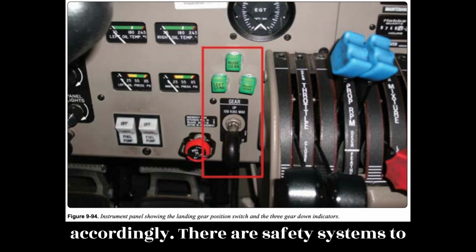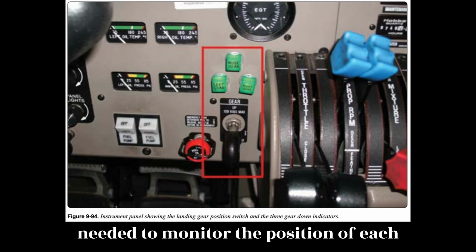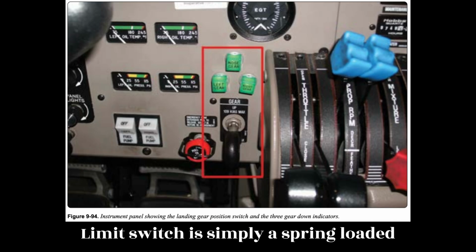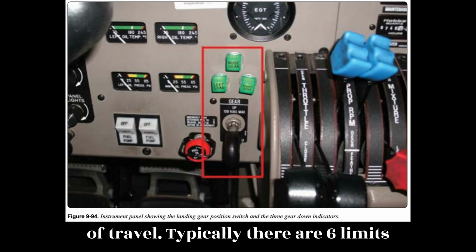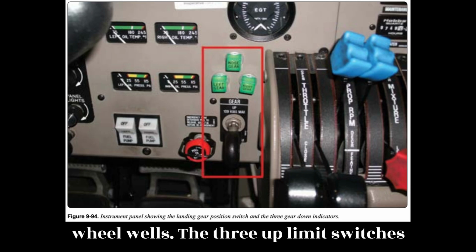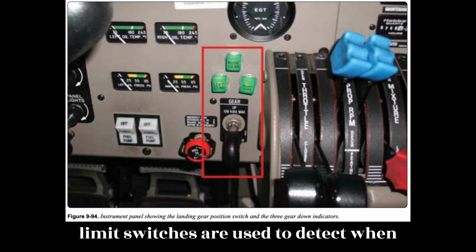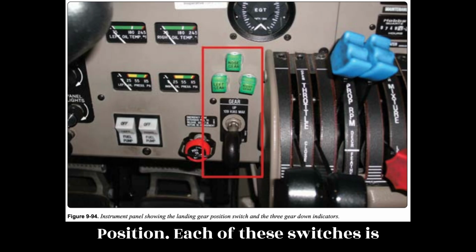There are safety systems to help prevent accidental actuation of the gear. A series of limit switches are needed to monitor the position of each gear during the operation of the system. A limit switch is simply a spring-loaded, momentary contact switch that is activated when a gear reaches its limit of travel. Typically, there are 6 limit switches located in the landing gear wheel wells. The 3 up limit switches are used to detect when the gear reaches the full retract, up, position. 3 down limit switches are used to detect when the gear reaches the full extended, down, position.